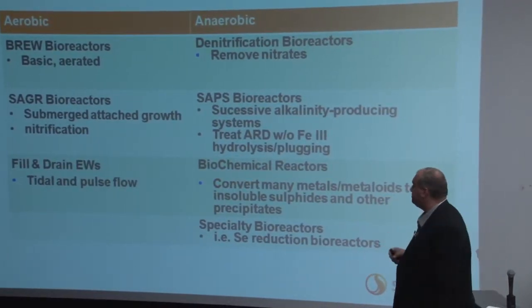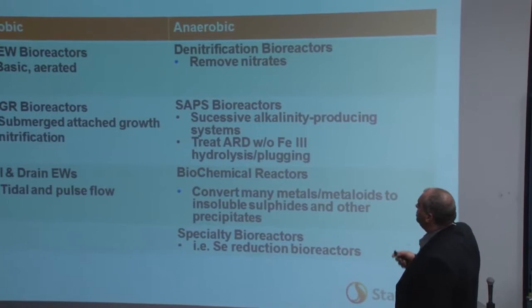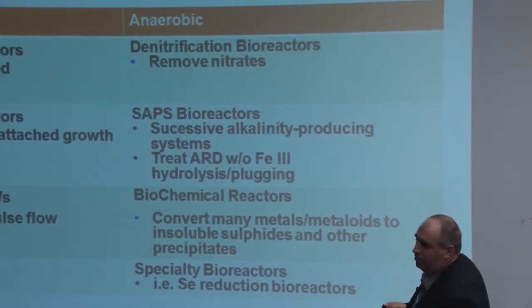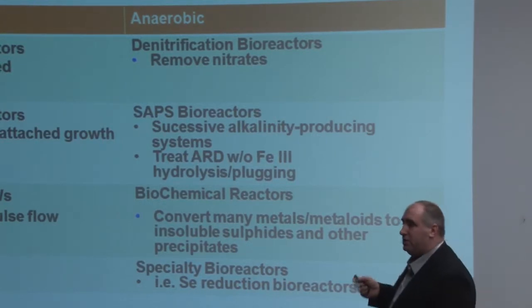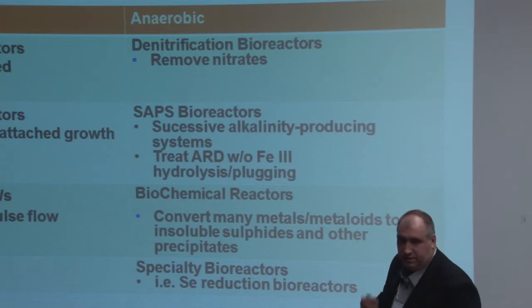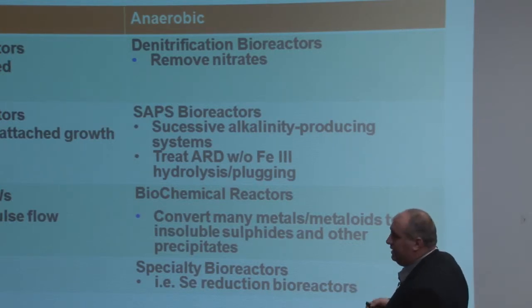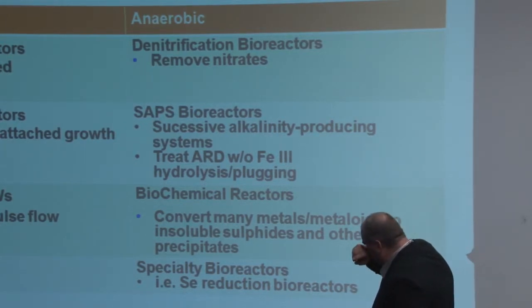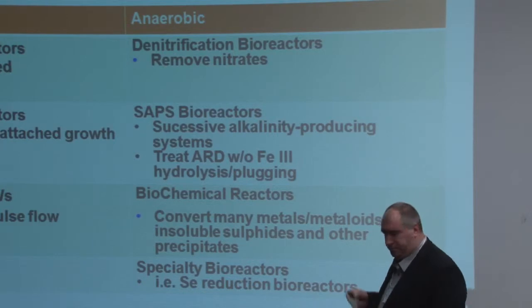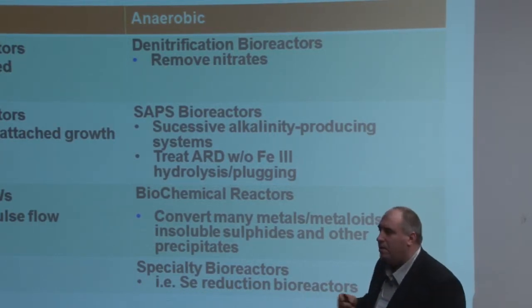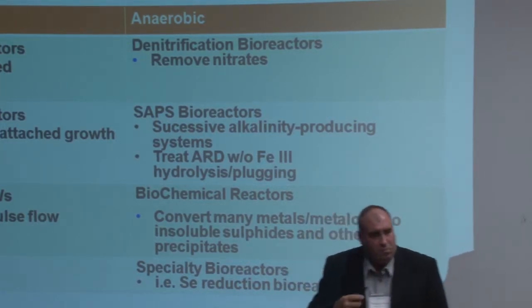Aerobic. Anaerobic engineered wetlands. We have denitrification bioreactors, which remove nitrates. We have SAPS bioreactors, which are successive alkalinity producing systems. So they treat acid rock drainage without iron 3 hydrolysis and plugging. This is a big problem in mining.